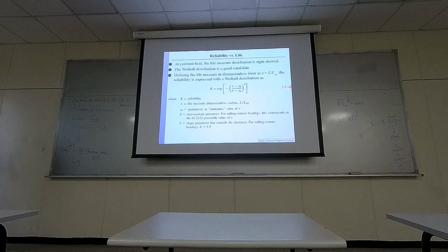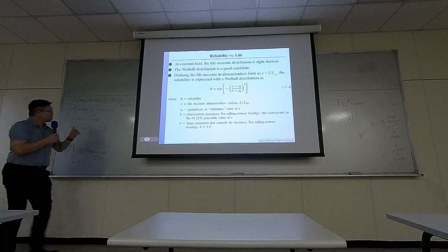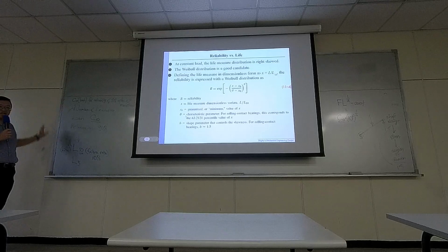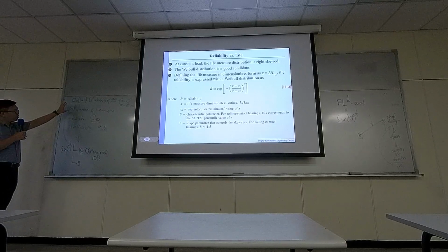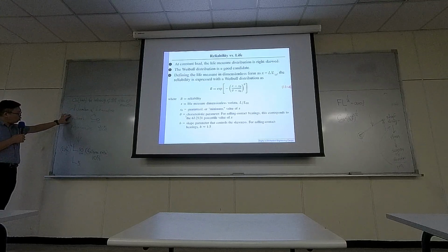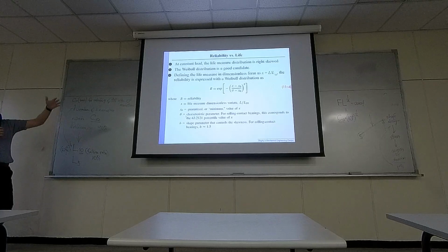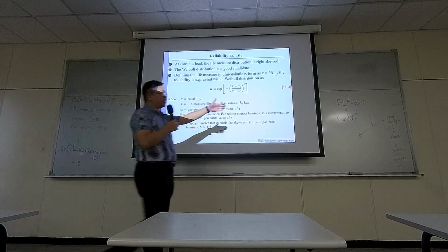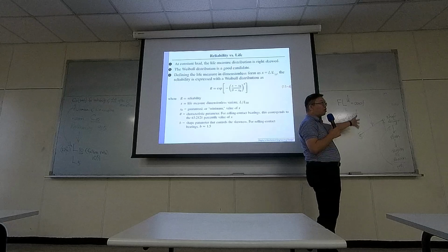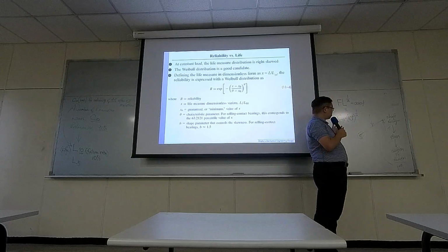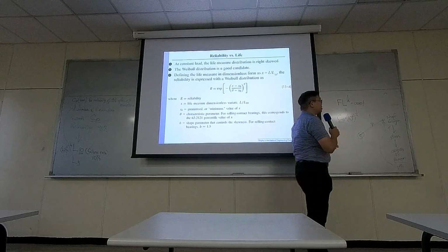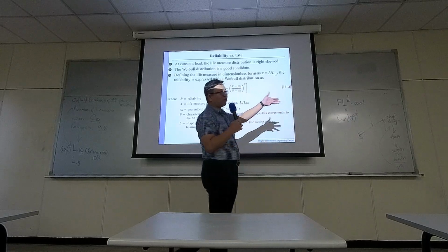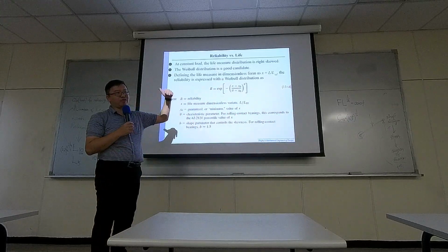for the design of bearing, generally we have relationships of revolution, load, and reliability. And we have this linear equation in the log coordinate. But that model is good for a certain amount of reliability.